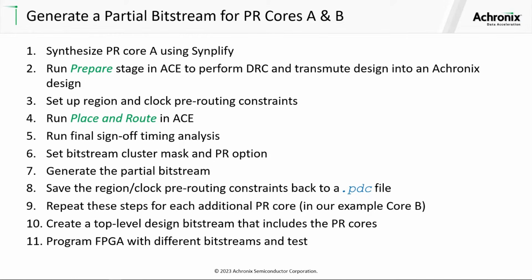Then within ACE, the Achronix CAD environment, we're going to run the prepare stage. That'll perform the DRC on the design and transmute that design into an Achronix design that our software can recognize and leverage. Then you want to set up your region and your clock pre-routing constraints. You run your place and route within ACE. And then, of course, you have to validate and sign off on your timing analysis. Make sure that it meets timing and the performance, therefore, that you're expecting.